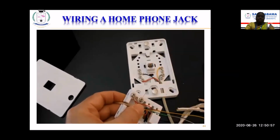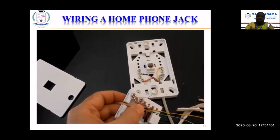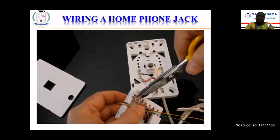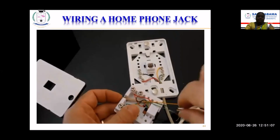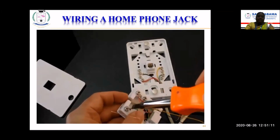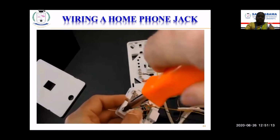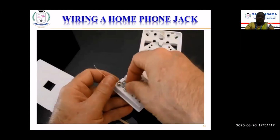And of course you've got this slack. You don't want to leave that. You can either wiggle it until it falls off, or if you've got a pair of little cutters, you can just cut off that little slack, because you don't want that slack in there. Okay, we don't need that. We don't want that floating around inside the jack, shorting things out. And then repeat the process for the green, and you can repeat the process for the black and the yellow as well, if you want to, or if you need to.